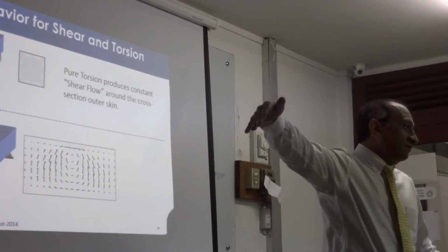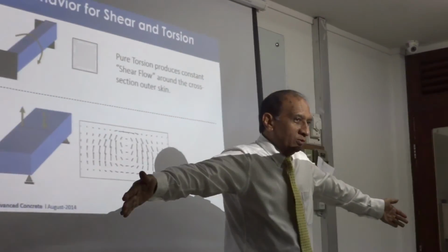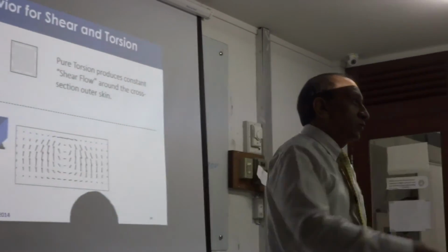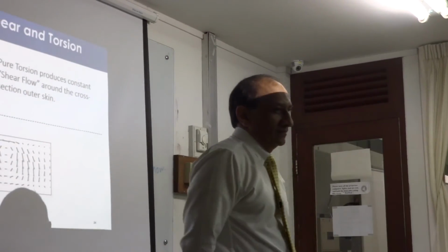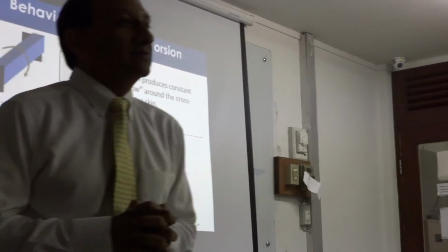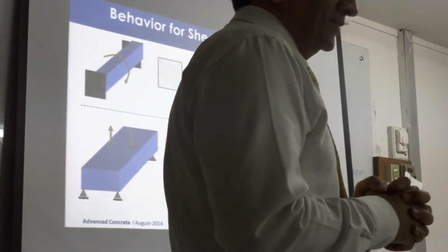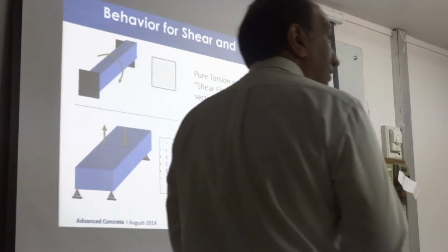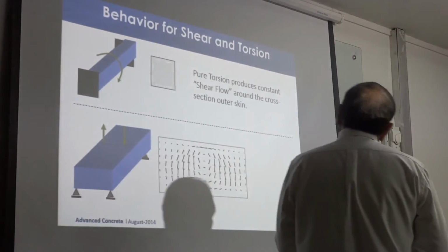MY, that should not be MX, please correct that. It should be moment MY. That means the moment is about the vertical axis, right? So you need AST depending on the direction, reinforcement here and reinforcement here and also in the middle, same way, right?